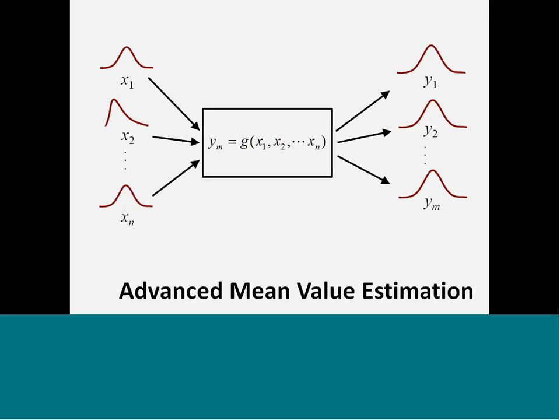So an alternative way of obtaining these data is based on reliability methods that drastically reduce the run times, yet still produce accurate results. This is done by estimating the confidence bounds and sensitivity using most probable point methods. There are several options and ways to do this, and here we're going to focus on advanced mean value estimation.